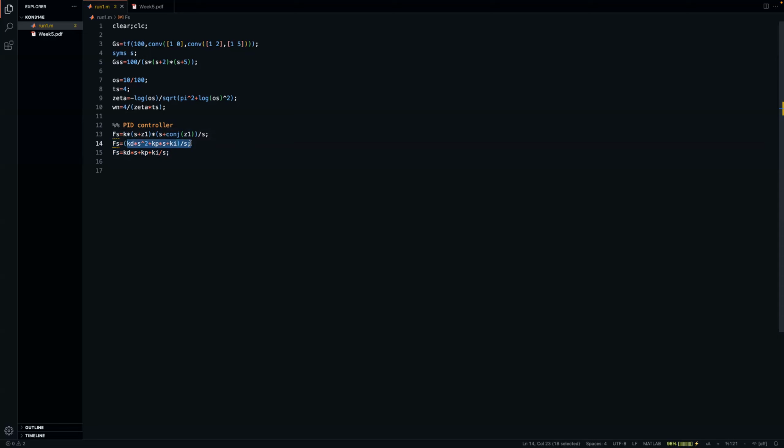And then the right-hand side is going to be the same, because residue times the desired polynomial, which in fact is actually already known, 2 times zeta times omega n times s plus omega n squared. So we know what zeta and omega n is. So this is basically a known polynomial. But the residual polynomial will be an unknown polynomial. So you will end up in a linear set of equations. And if a certain thing can be linear, then we want to have that, because it will be much easier to analyze and solve such linear equations than nonlinear equations.